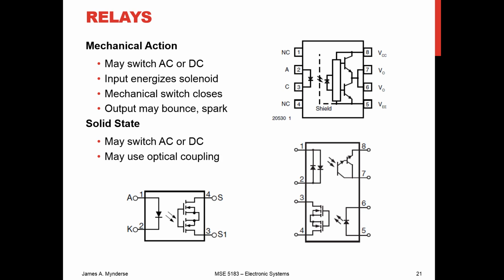So in this bottom left here, you can see that we've got two transistors. These are phototransistors. These are not BJTs. You can see they're actually FETs. Over here, this is like a photo Darlington pair. Up here, we've got what appear to be, that's either a photodiode or that's a phototransistor. So we've got these different options, right? We can make different types of solid-state relays.